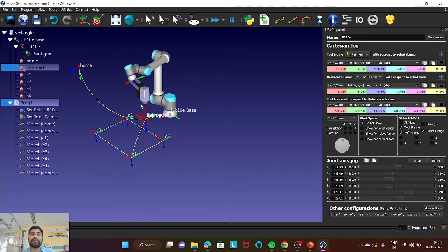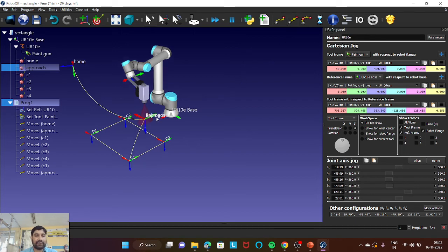It is not possible to achieve the particular position. That is called linear singularity. So to avoid that, wherever possible, you must give joint moves and should not go for linear movement. If you give the linear movement, the singularity error will come.